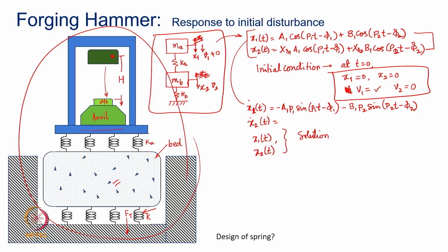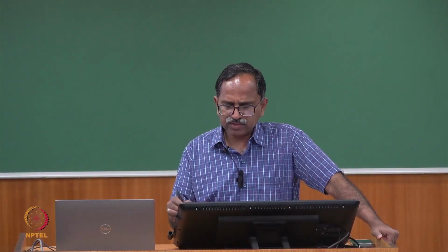Once you generate the response, the last step, which was a part of the vibration analysis, is to interpret results, right? Just generating a response, if I plot this response as x1(t), it's not going to be harmonic, and I would expect you to know and understand why it's not going to be harmonic, particularly for this initial condition, not for all. But so this will be some response.